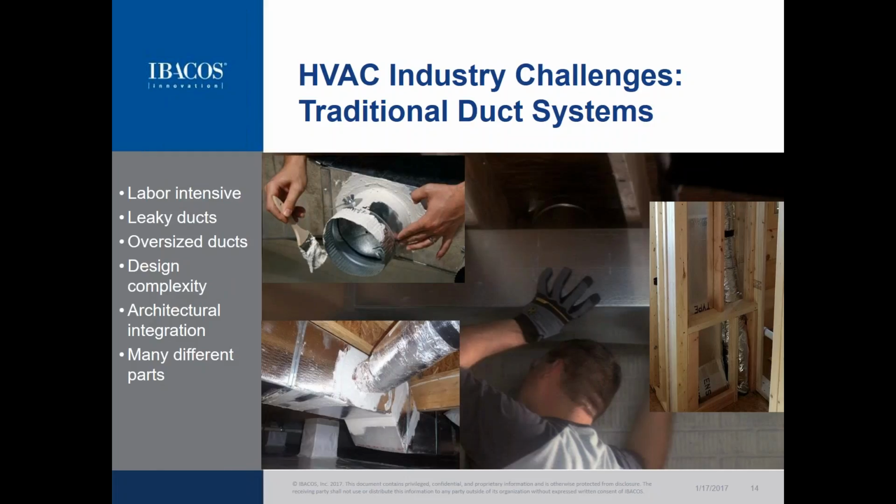So from a traditional duct system, this is typical. We're seeing a lot of sheet metal and a lot of flex duct systems. In sheet metal, it's very labor intensive. It's basically pieces that come to site that have to be field fabricated and sometimes custom fabricated in a sheet metal shop. All these connections need to be airtight, so they have to basically install a lot more sealant, whether it's mastics or tapes that have to be installed, so there's a lot of time that gets incorporated into the installation.